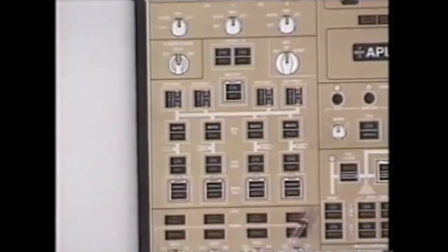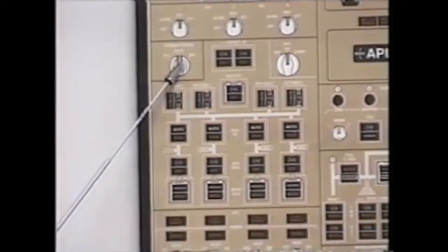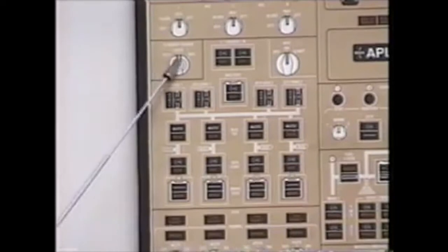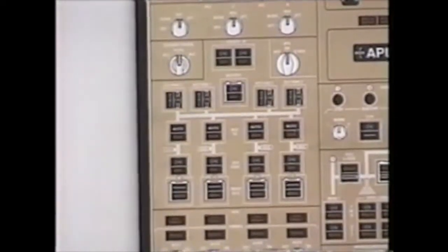Continuing our discussion with the electrical panel and the overhead, the standby power switch again controls both the APU and the main standby buses. If the airplane was fully powered with the standby power switch in auto, moving the standby power selector to off will kill both the APU and main standby buses.